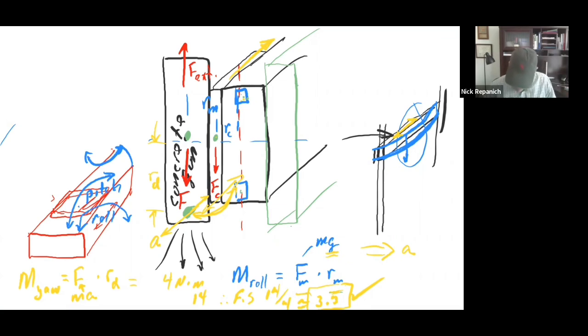So let's deal a little bit with non-moment loads. Let me go to the next page. So in this diagram, I'll just put it back up here real quick. We've got this gantry type device with a cross axis to it. There are 2 different kinds of loads that you would look up on a stage. Some of the loads are moments and some are just forces.